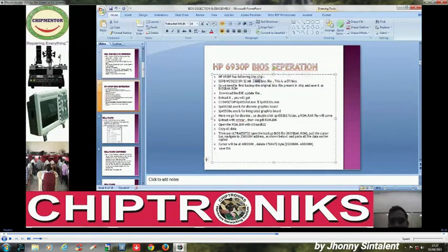So what we'll do, we'll open this rom.bin, we'll copy all the data, we'll again open this BIOS back.rom, we'll go to the 2508 address, we'll paste it, and we'll delete all the data after 400H, because we require data up to here. This is our 4 MB data. We will delete all the remaining data and we'll save. And this is our system BIOS file.